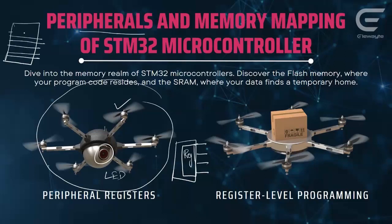So like this memory is formed. So let us say this is 0x0000, 0x0001. Like that, we have different registers present in the memory. So this is called memory mapping. That means which register is present in which memory.